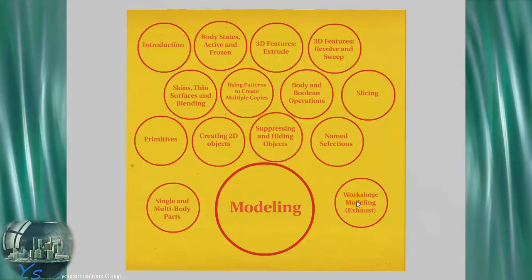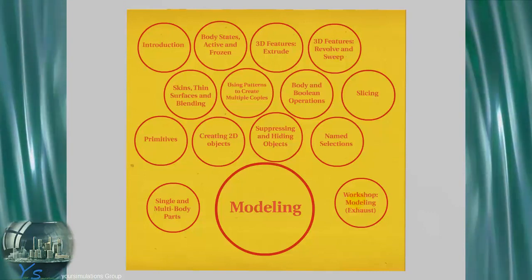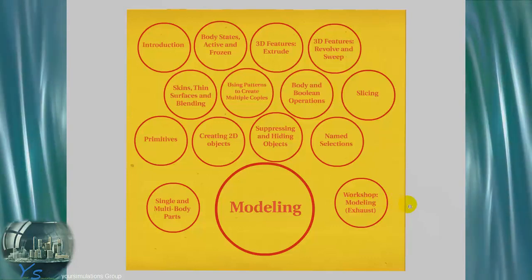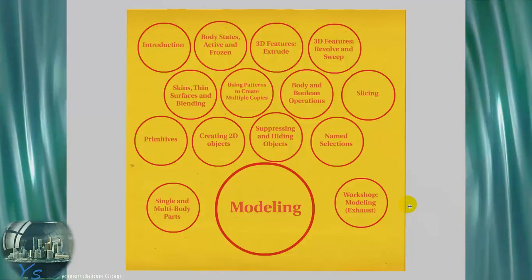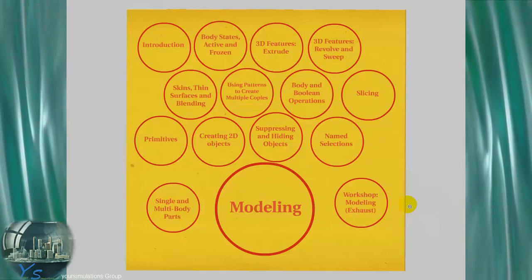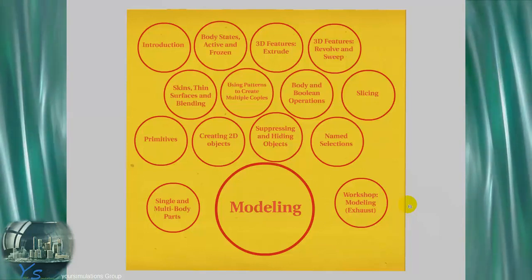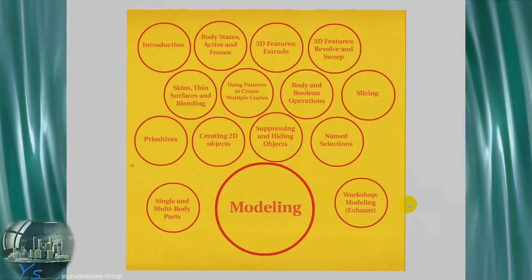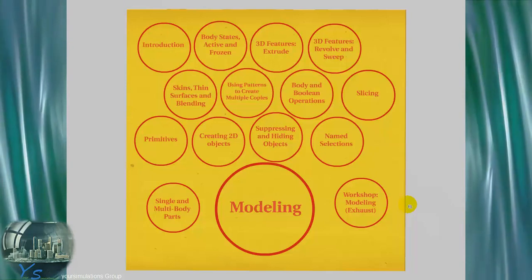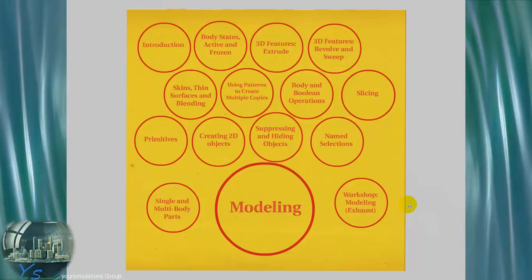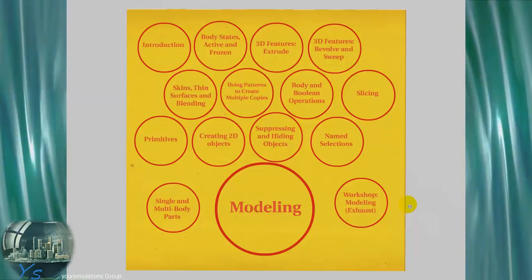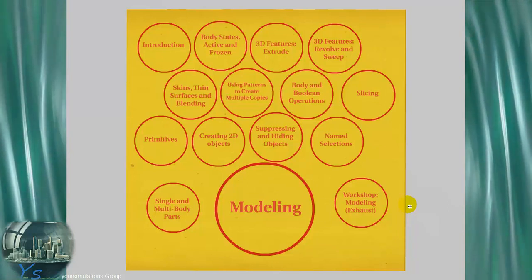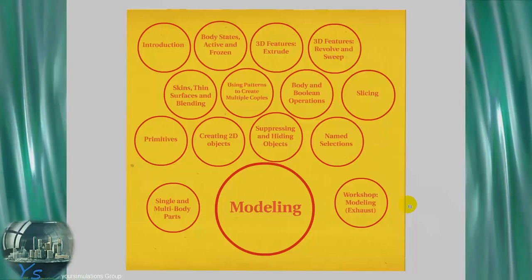We'll talk about some of the concepts in terms of the body types and states of bodies, creation of 3D geometry, modification of geometry. We'll also talk about creating 2D geometry and some concepts to be aware of in the geometry stage in anticipation of the next step in the simulation process, the meshing step. And the key items there are discussing multi-body parts and sharing of topology.